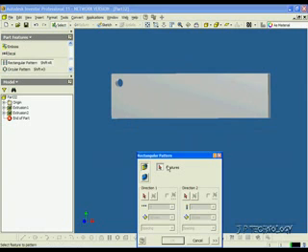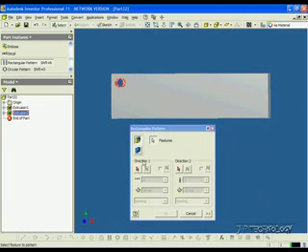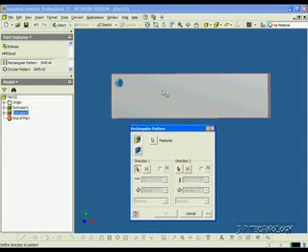Now to use the rectangular pattern feature, what we have to do is go down and select it. And the first thing we have to do is click the feature that we want to pattern. You can do this two ways. You can either select it by clicking the actual circle, or you can use it by clicking the pattern in the tree. I suggest using the one in the tree because it's a lot easier and it's a lot more precise. So let's click it. Then you have to choose the direction. So let's click the arrow there, and you're able to choose a line that you want it to follow. So to start off, let's click the top line here.